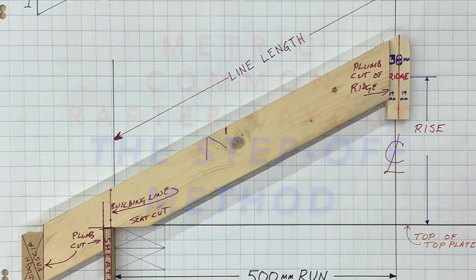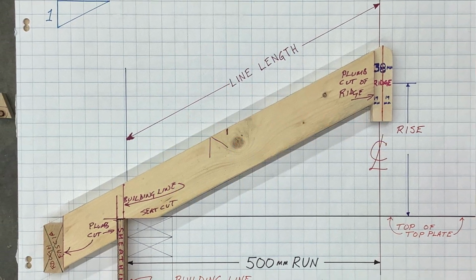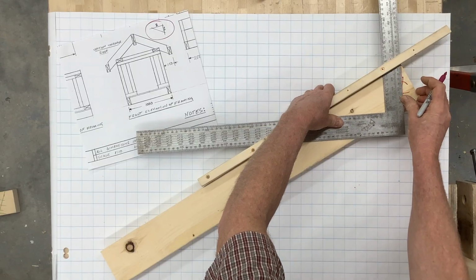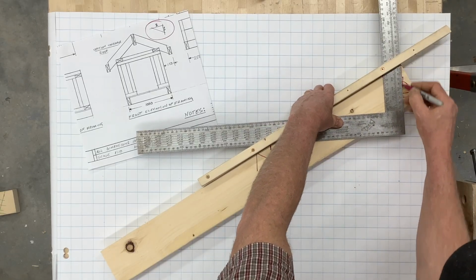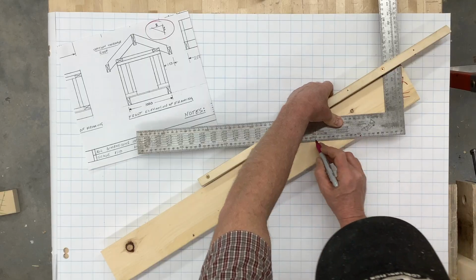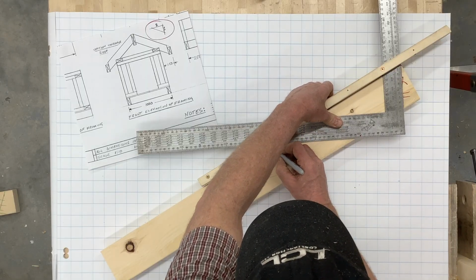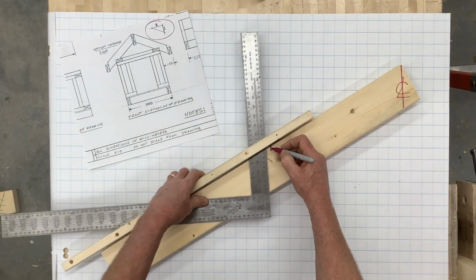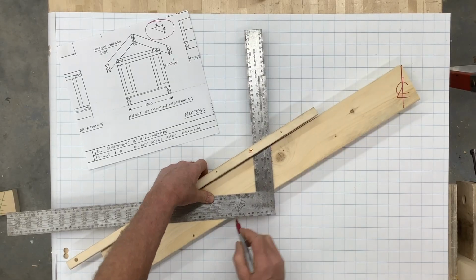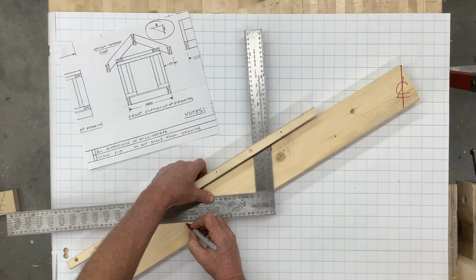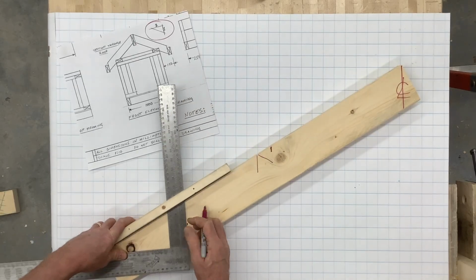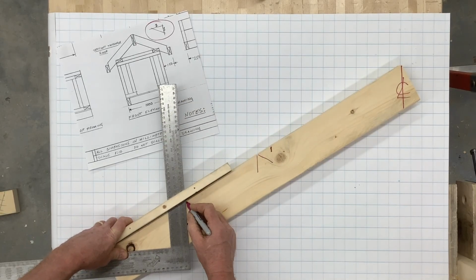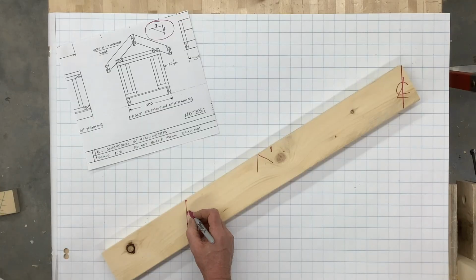The fastest and easiest way of laying out a short common rafter is by using a carpenter's framing square and the step-off method. In the step-off method, the framing square is set up with either stair gauges or a fence set to any convenient multiple of the rise and run of the roof slope. Then, the run of the rafter is measured horizontally from ridge to building line.